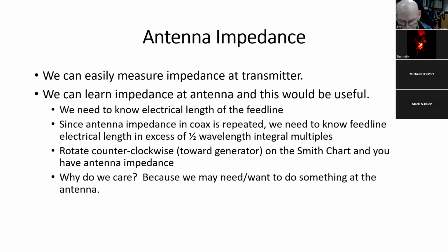And in the case of living with what we've got, I've got this random offset center fed dipole with a 4-to-1 balun on it that I threw up 20 years ago to get something in the air and something on. And I'm learning as I spend more time on 75-meter nets and as I work military stations on the West Coast and in the Gulf, that antenna works actually a lot better than I ever expected it would. But it definitely needs a tuner. And I will be looking into, all right, is there something I can do at the antenna to broadband it?